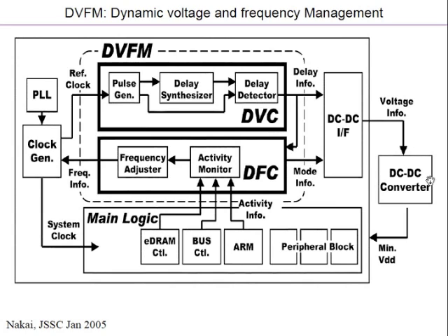They also have a voltage DC-DC converter, and there will be a supply source here. From there, the DC-DC converter generates the voltage based on what the controller tells it. The controller will say, reduce the voltage, it will go and reduce it, and then the new voltage will come. And then you see out here, the PLL, which is the clock source, clock distribution, etc., are kept outside this voltage. They are running at a fixed voltage. There are certain things which have to run at a fixed voltage, the IOs, the clock generator, etc. But a lot of the things can have adjustable voltage.